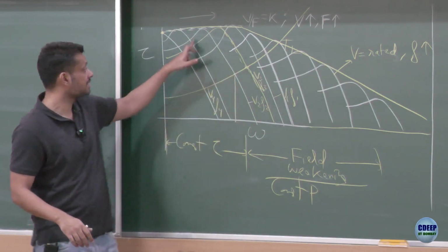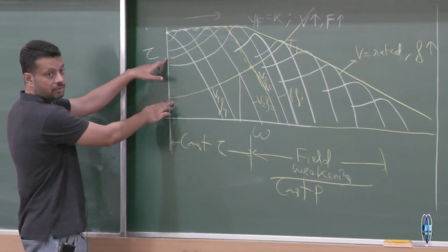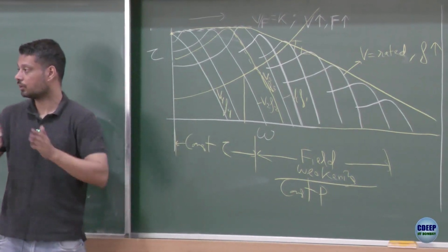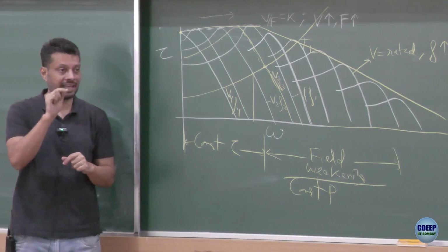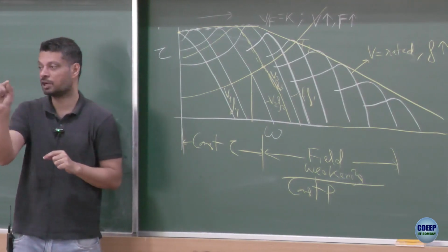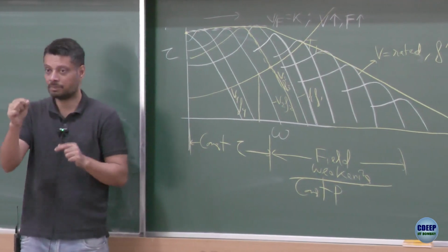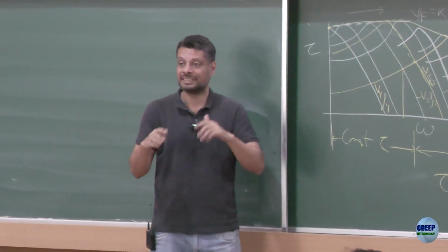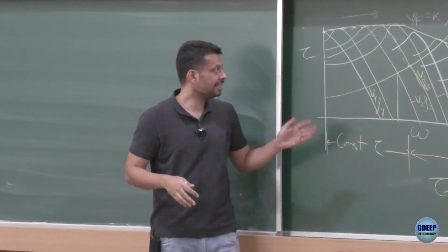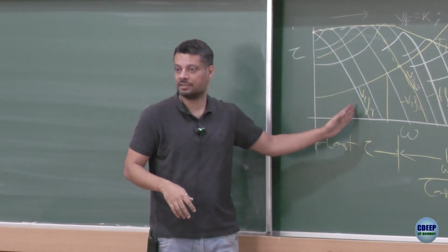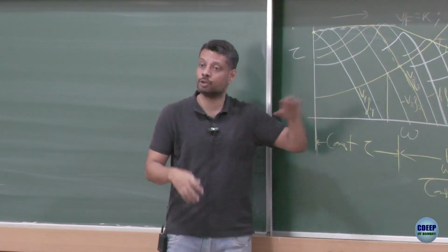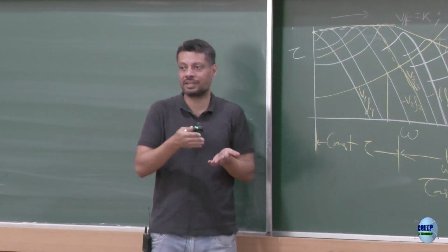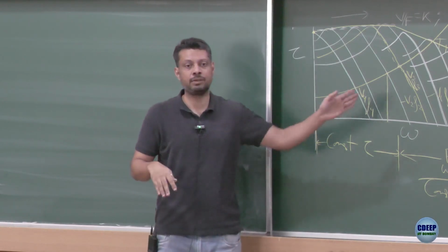Because F3 characteristic is this one. This is your load characteristic. You won't get the maximum torque, you would get a large inrush current, all the problems would be there. So although on the drive display you were setting 45 Hertz, there is a processor inside which knew that you eventually want to run at 45 Hertz, but it would do a soft start. It would initially apply a very low voltage and frequency, then it would slowly increase the voltage and frequency over a few seconds, estimating that the motor would also take a few seconds to go from this speed to that speed.